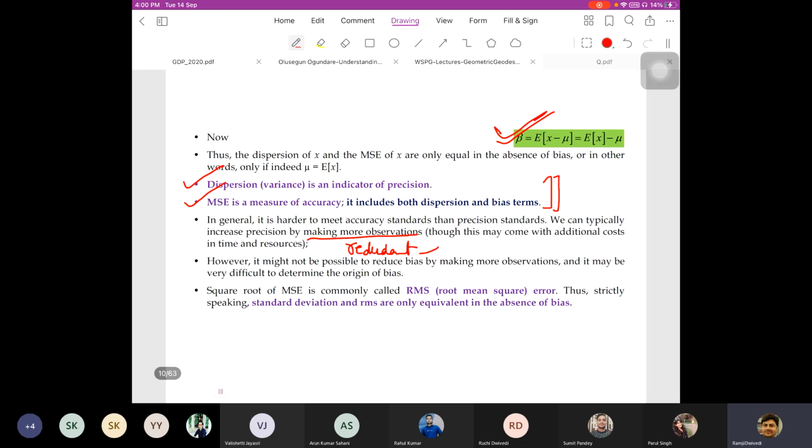Very good line. This should be your basis of understanding from now onwards: you have RMS, and you have standard error, and both notations are different. Sometimes people simply call it RMSE, and they do not represent it with any sign like sigma, they just write RMSE. But the standard deviation has a very unique sign, sigma. So this will prevail if random error is there, and RMSE will prevail if, obviously, you cannot ignore random error in any observation, plus the bias.